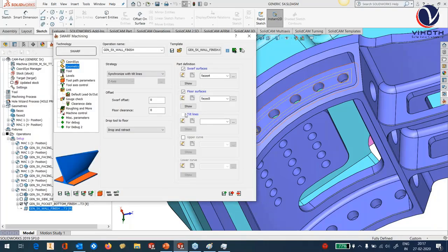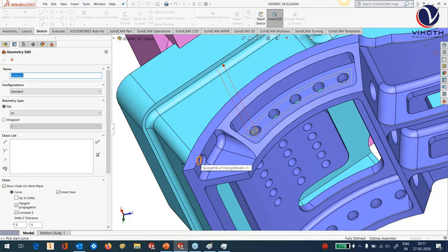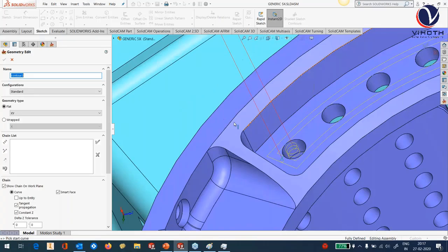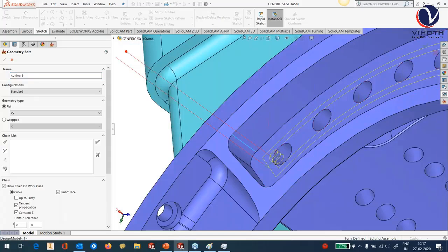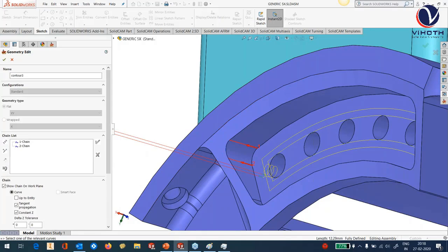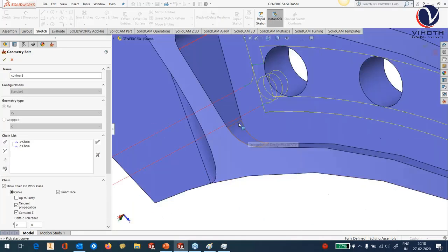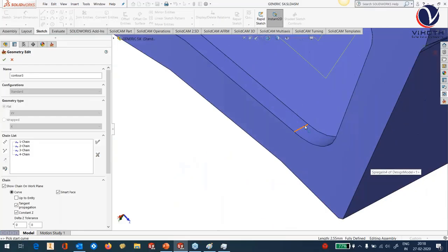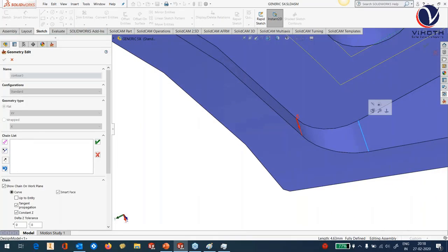I'm also going to use tilt lines because I want to control the tool axis. I don't want the tool to dance in areas because some of the surfaces are not great because they have different ISO lines, they have different width, but that's the reason I would like to define tilt lines, simple tilt lines, 8 of them. So just pick 2, the third, okay, fourth, then you have the fifth one, sixth one.